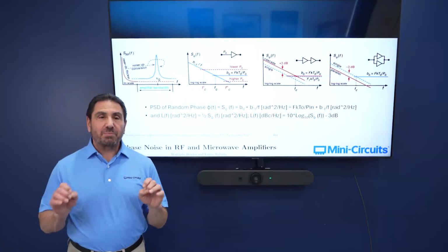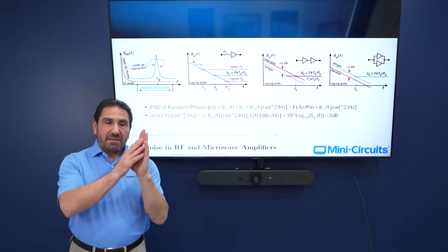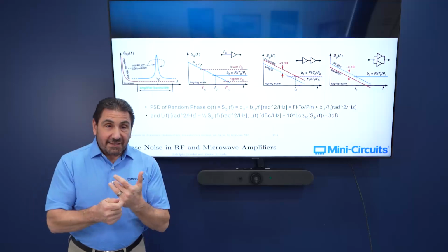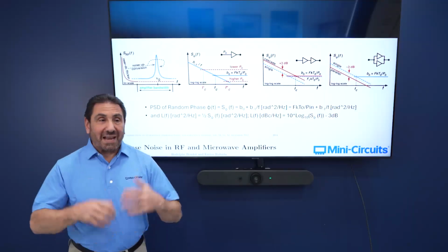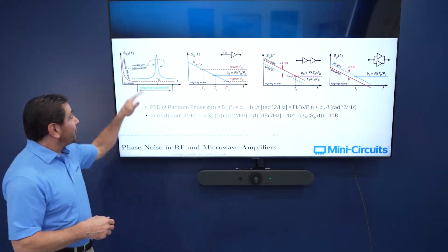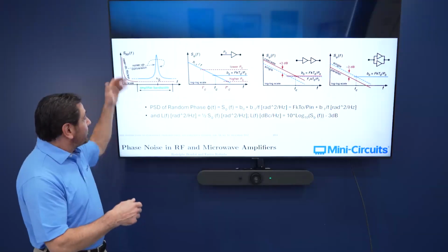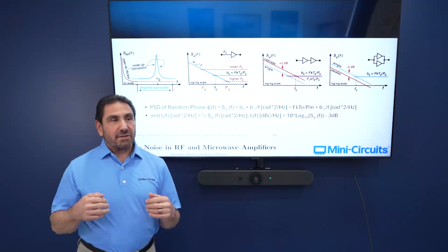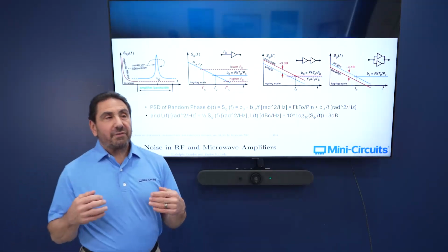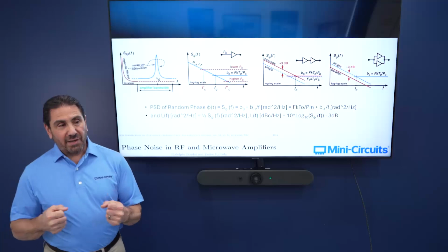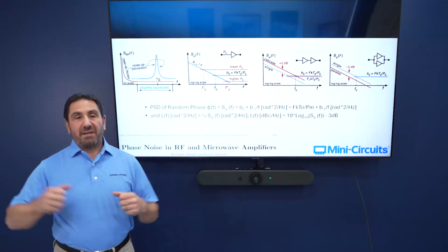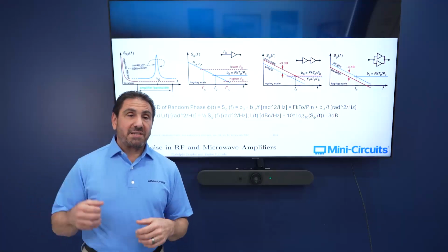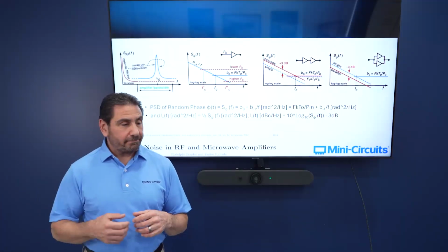And this is a baseband spectrum, occurring very close to DC, and it comes out in frequency as a function of the device technology and the biasing circuitry. Everything you do to that amplifier will affect the amplitude and the bandwidth of that flicker noise. Now, in many circuits, we have predominantly two different categories of amplifier: bipolar and FET-based. Our bipolars are realized with HBTs, and the FET-based are realized with PHEMTs.